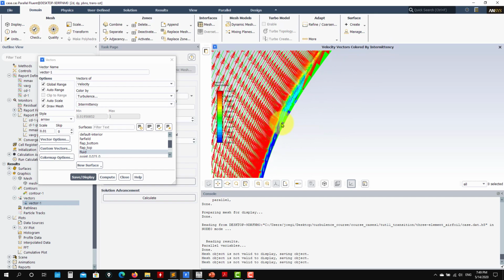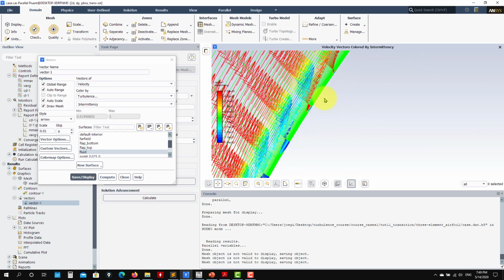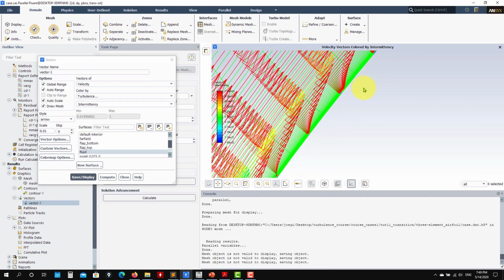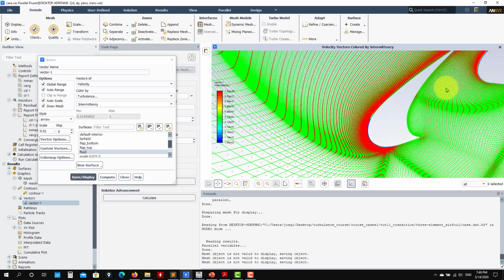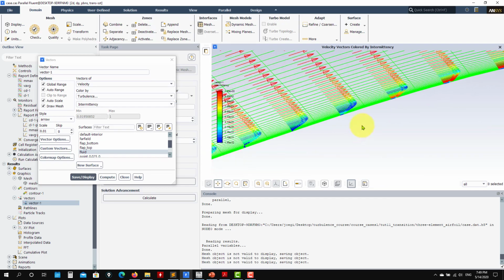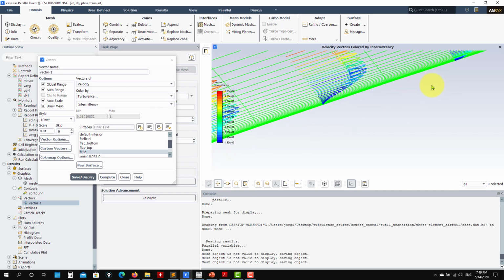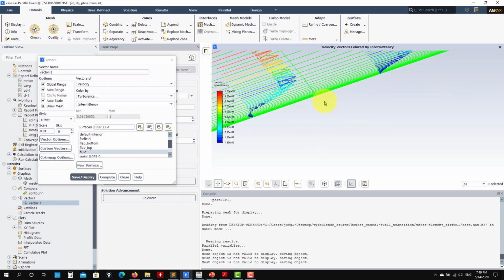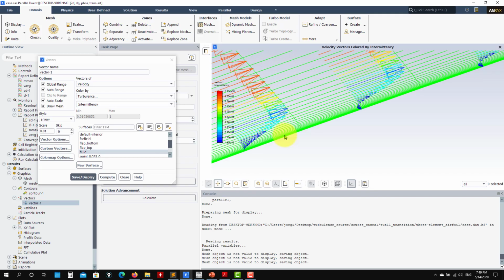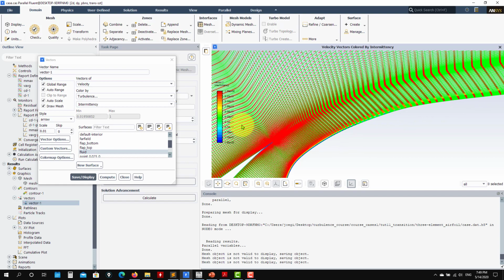But here in this separation bubble, the flow is laminar, and then as soon as the flow reattaches, it becomes turbulent. See that here it reattaches and is fully turbulent. Okay, and then if we move back to this end, we're going to see, I think, a smaller bubble. Probably it's not smaller, but it would be better to add more cells here to better capture it. But here you see that you have that bubble reattaching and then fully turbulent.